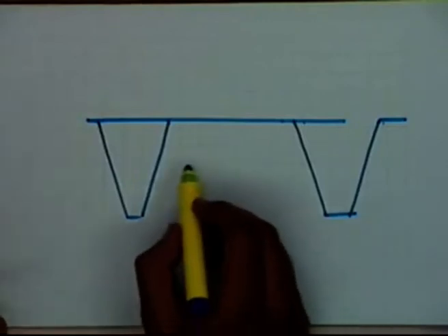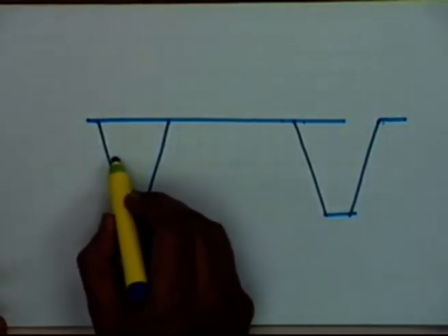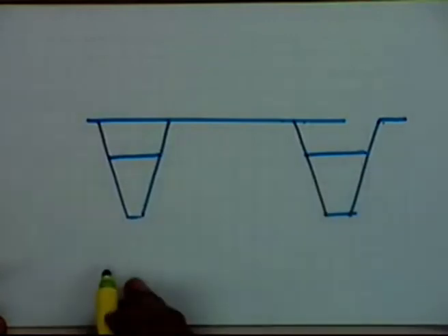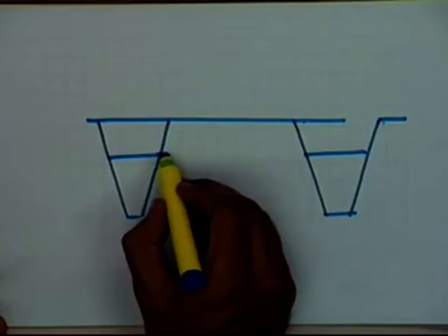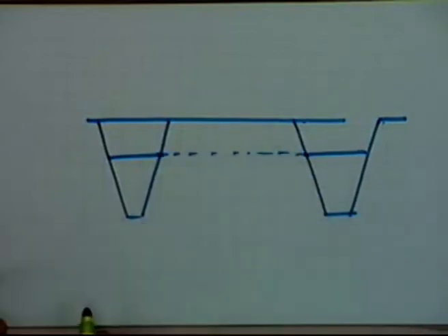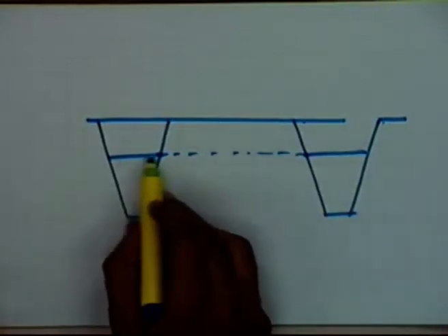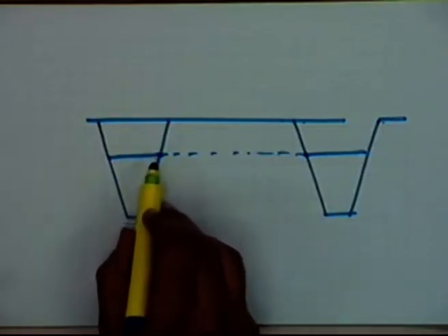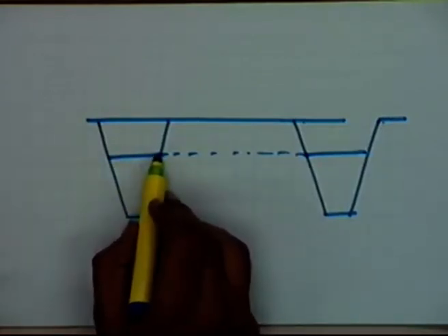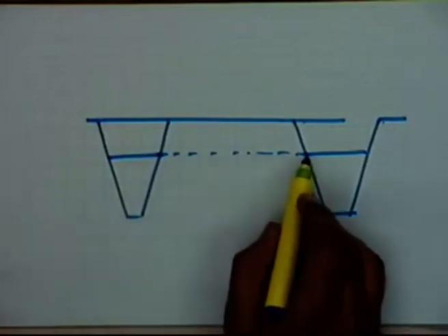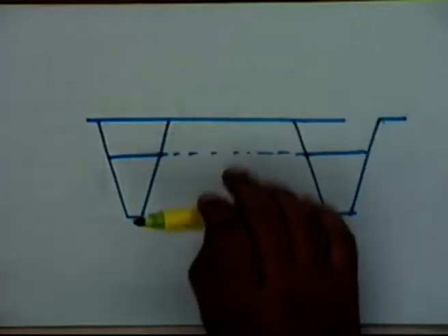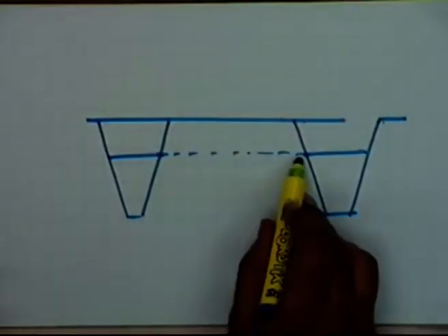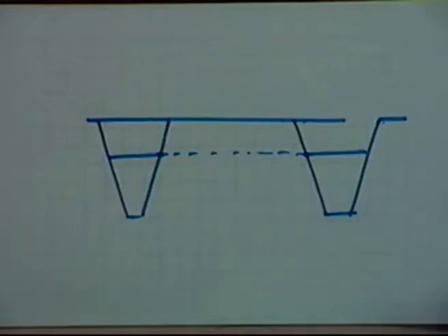Now in this particular case, by controlling the level of water, if my previous water table was, this is the water table which I have established after controlling this level for a long period, you will find that this will stabilize. The water will keep on moving on this side, and depending on the soil type, if the soil type is quite porous, this might be achieved relatively in a quicker manner.